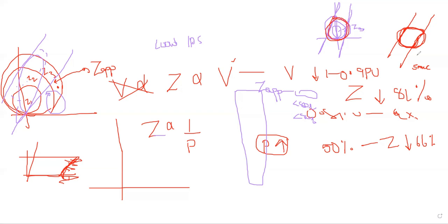In the articles, wherever, in the IEEE also, power swings and load encroachments can be handled by these characteristics only, by using the blinders or by using the lenticular characteristics or quadratic characteristics. I think what you said, like 5 seconds, 0.5 seconds, that is a concept of disturbance recorder. Maybe I'm not sure about that. Maybe that is the one.